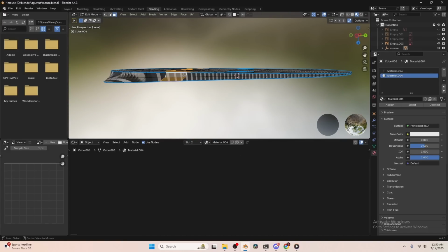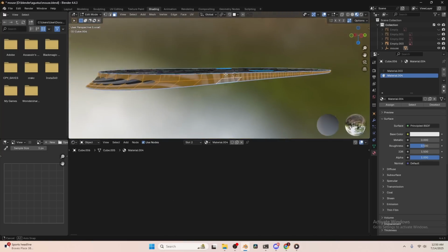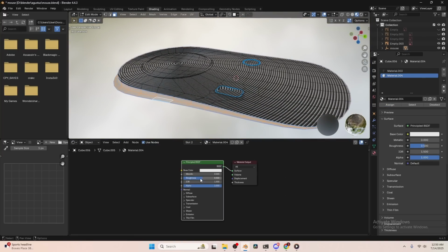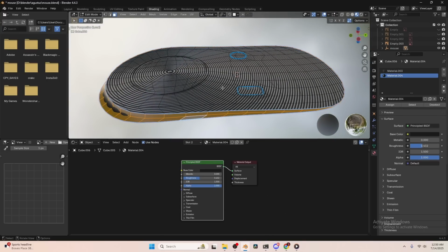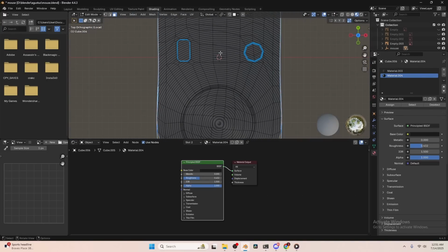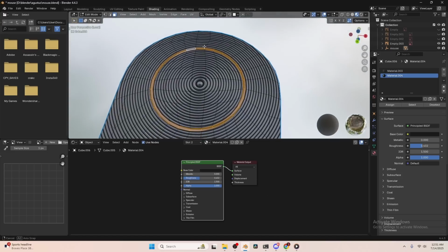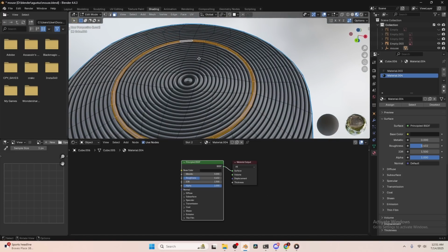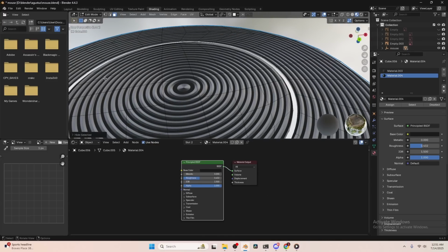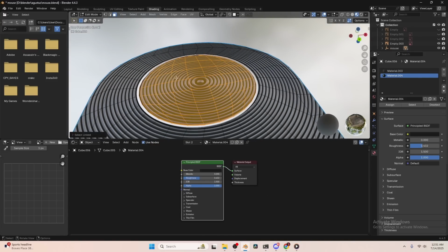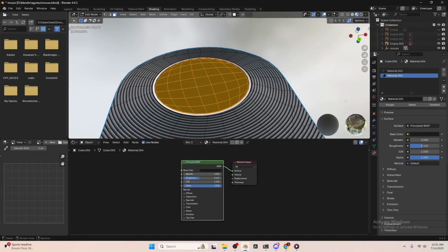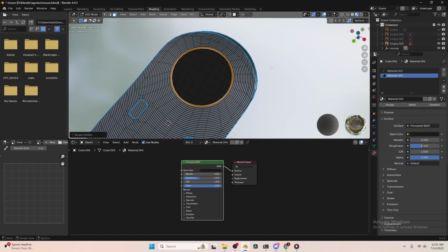I'm going to select all of these faces, just like this. The new material, click assign, turn down the roughness and change the color a little bit black. Okay, and we can do the same with this one. Press 3, change to the face mode, I'll click here. I'm going to press H to hide this edge, press L, then click assign here, Alt H.